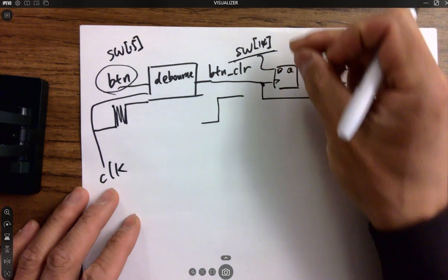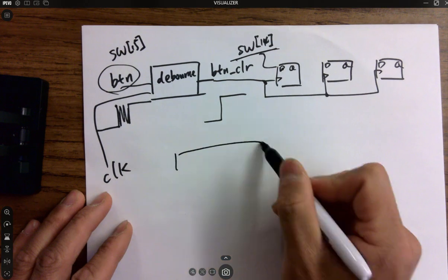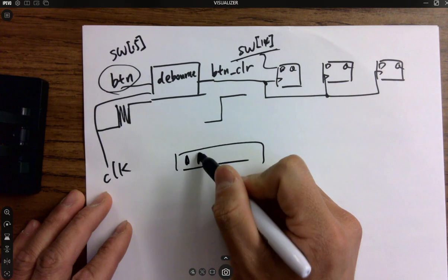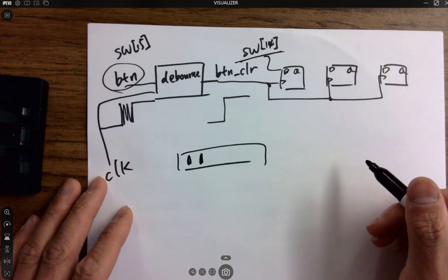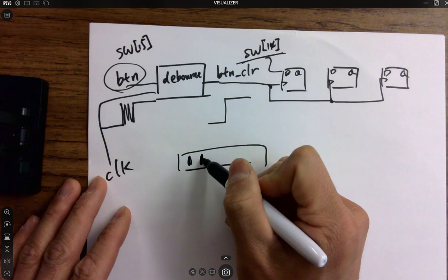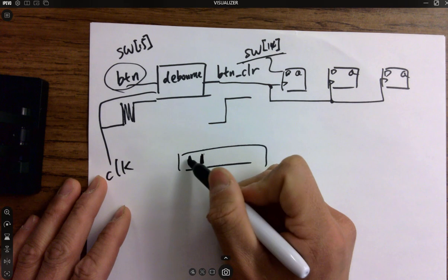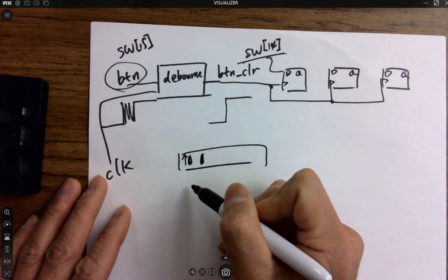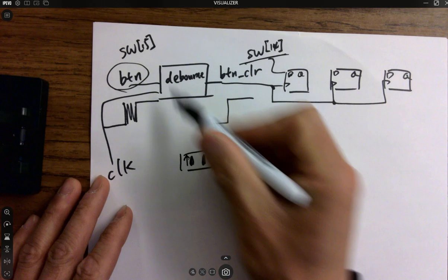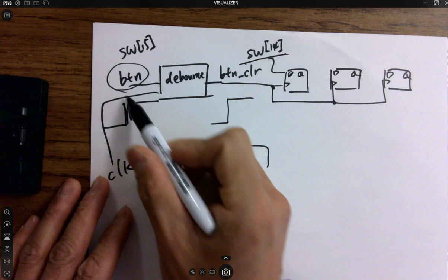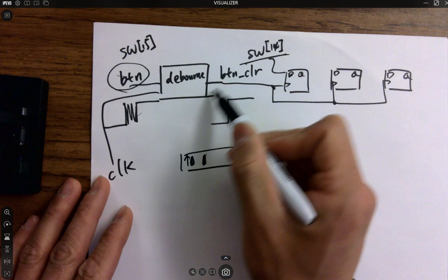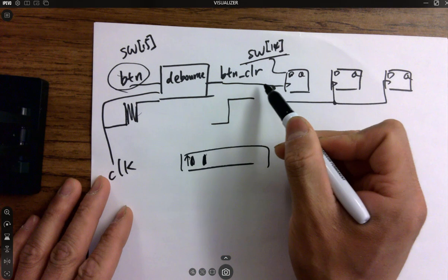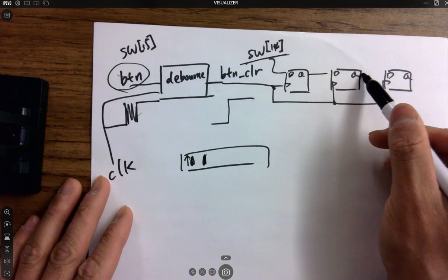So you have 2 switches, right? One's here, one's here. You give a data switch, you give it 1, you have a 1 here, and then you give a rising edge and pull it back, just push and pull it back. So give a rising edge to the switch, so switch 15. So this one will create a clear rising edge for the serial in, parallel out.